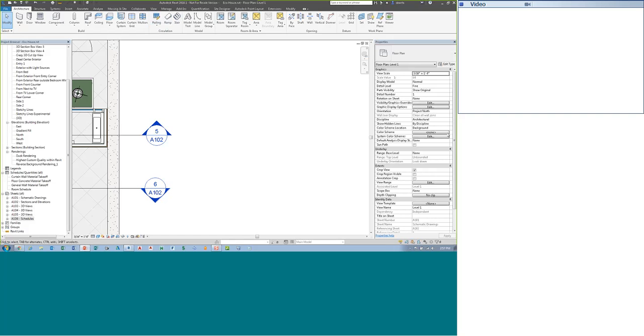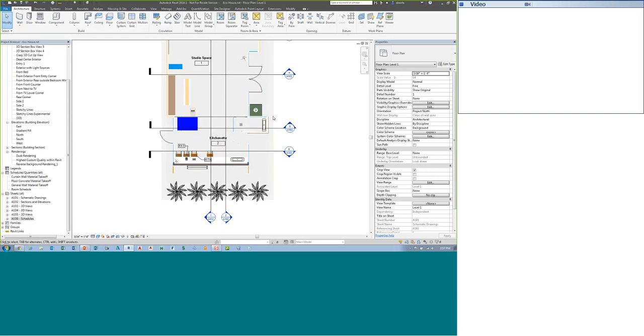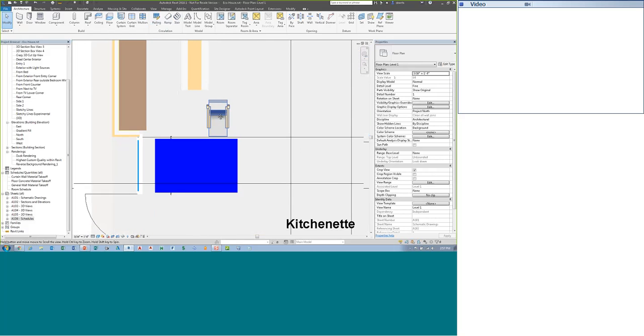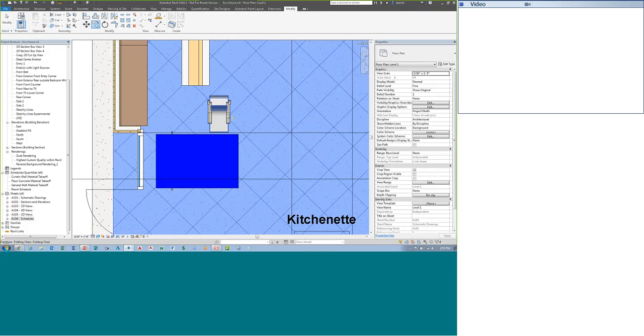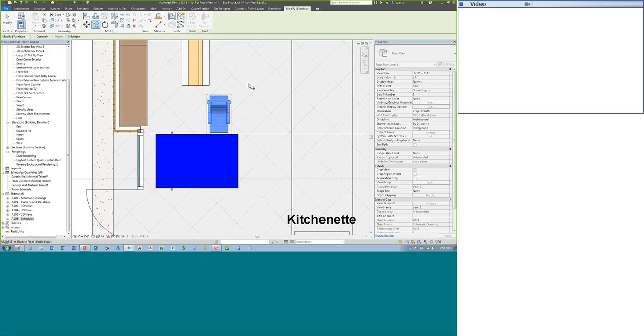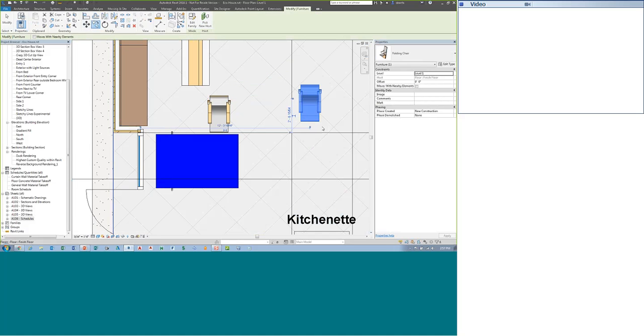Let's take a look at command number 5, the copy command. The copy command is very similar to the move command. So head over to the Modify tab of the ribbon. I start with the copy command. I pick the entity. I'm finished picking objects, so I hit Enter or Spacebar, or even right-click and finish selection. And then when you go to copy, you're asked to specify a start point and then an alternate point.